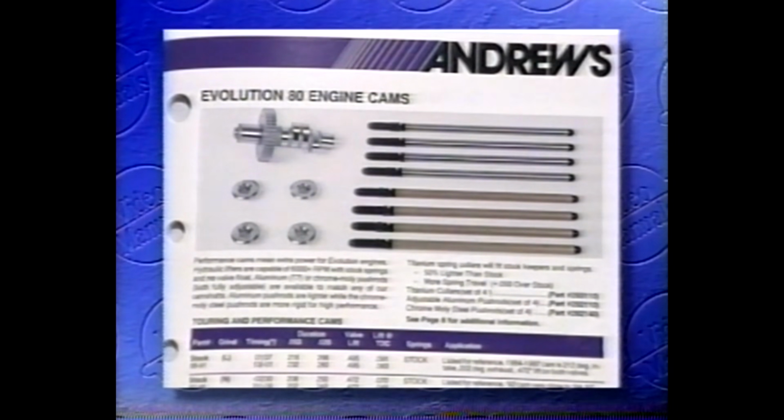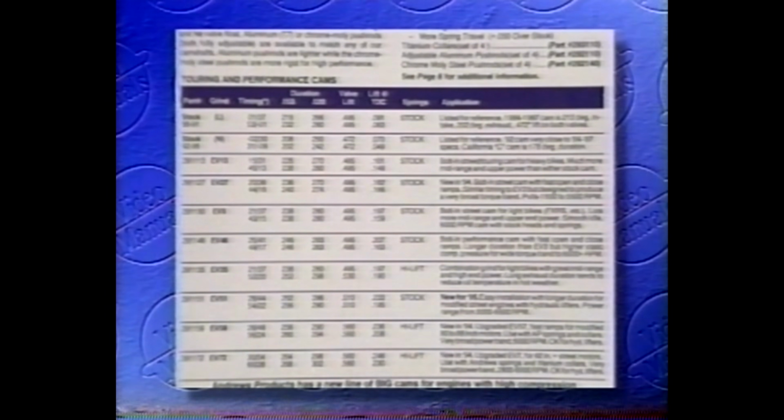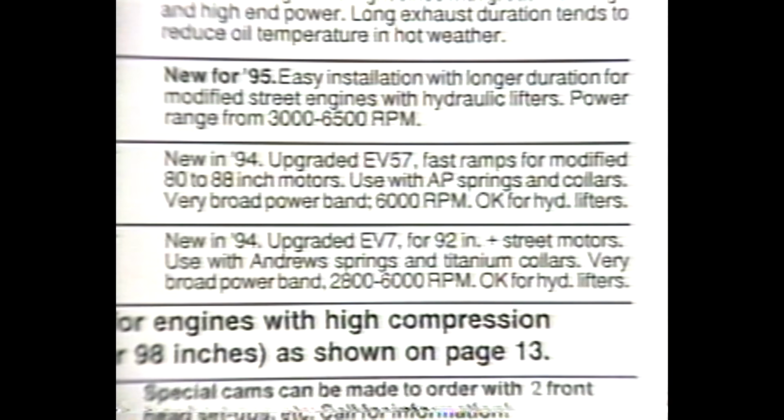We always refer to the cam manufacturer's specifications for correct spring pressures and tolerances. The faster a high-performance asymmetrical cam opens or closes a valve, the stronger the spring pressure required to prevent the valve lifter from losing contact with the cam lobe surface at high RPMs. Insufficient spring pressure will allow the valves to float off their seats, thus changing our timing.